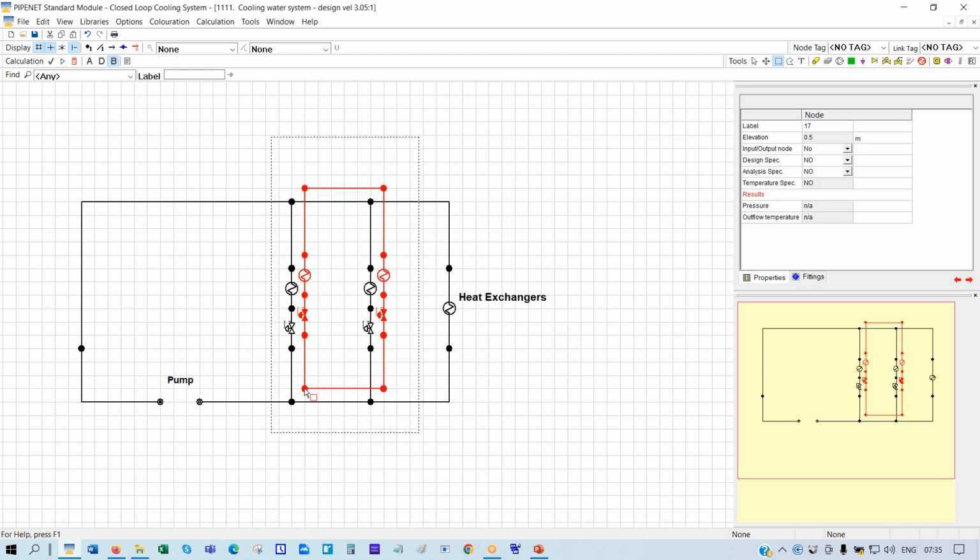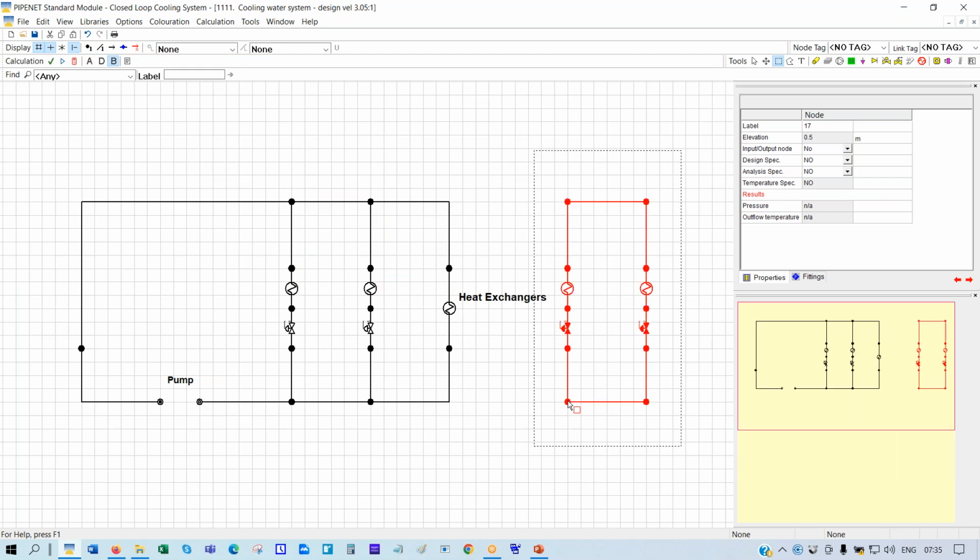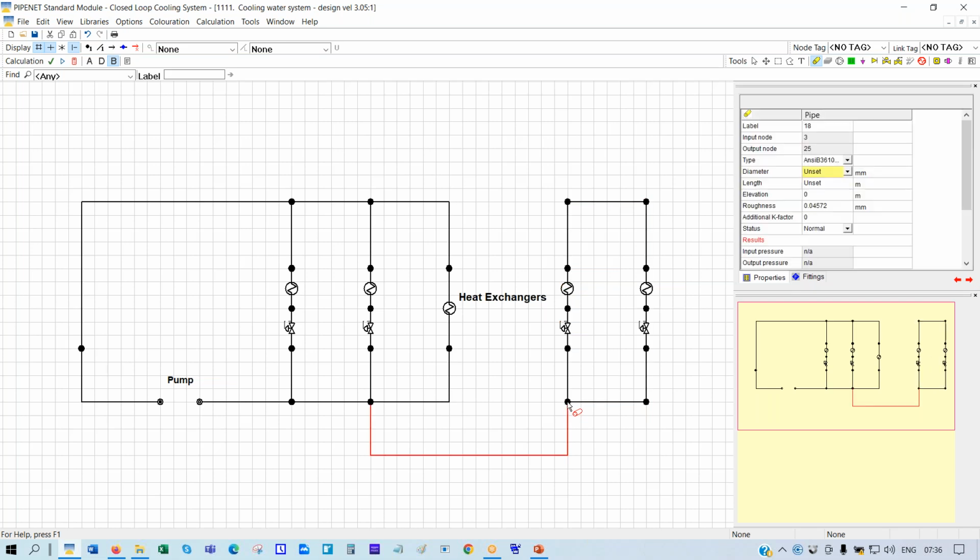It's convenient to pick a node so that you can more easily position. I can move it. Then I can pick up the pipe tool. I want to create a waypoint. Press and hold the shift button. Click on the left button of the mouse. Do the same again. I'm holding on to the shift button. I want to create a node here. So I release the shift button and click. I do the same on that side.